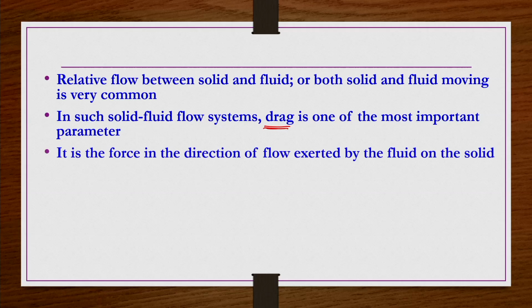What is the drag? It is the force in the direction of flow exerted by the fluid on the solid, right. Let us say we have a particle, and there is a fluid coming in here like this. This fluid is approaching this particle. Then, depending on the flow conditions, streamlines may be developing like this. The surface of this particle may be experiencing some force because of the fluid, or the fluid is exerting some force on the solid object surface.